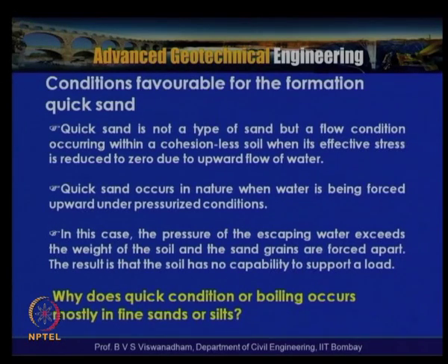So, quicksand is a terminology that comes up when there is a loss of effective stress that happens drastically because of this phenomenon. What we discussed is that when water flows upward through the soil, the soil loses all its strength and supporting capacity, and we get a phenomenon called quicksand. So, the quicksand phenomenon is basically a condition where water flows in the upward direction, and there is a possibility of the loss of effective stress.